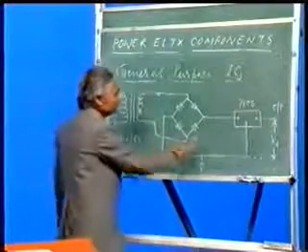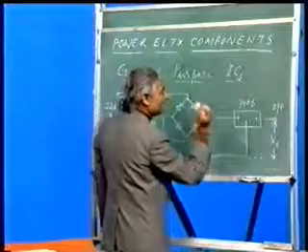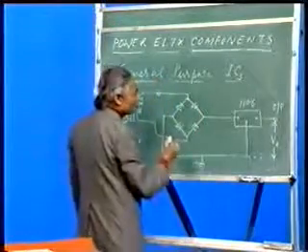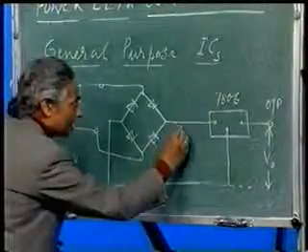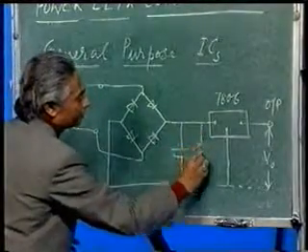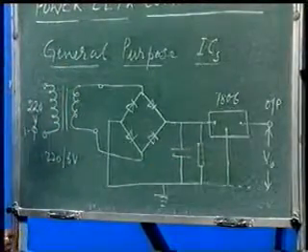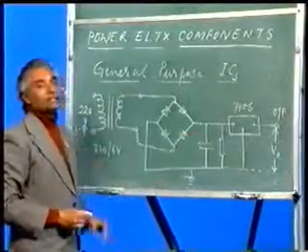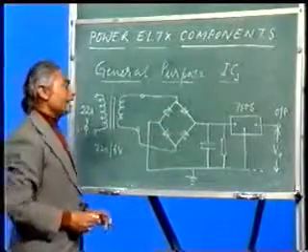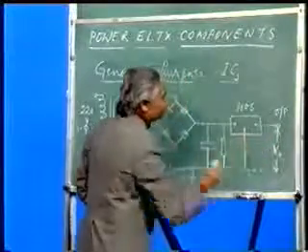Now this is given to this 7806 and the output is V output, which has to be regulated 6 volt. If I want to nullify the ripples, I can put a capacitor here and also a resistor. This does not mean anything special, this just forms a filter circuit. So filtering is done and here you will have a very good DC regulated voltage as output.